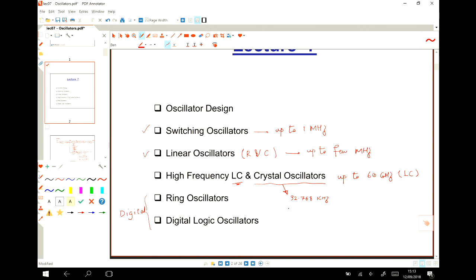I mean, a few versions of them which are available in high frequency, hundreds of megahertz or so, are available, but they are not cheap. So usually we are using crystals, and then you will see in the next lecture that we are using PLLs to make higher frequencies out of them. Multipliers and PLLs, okay?